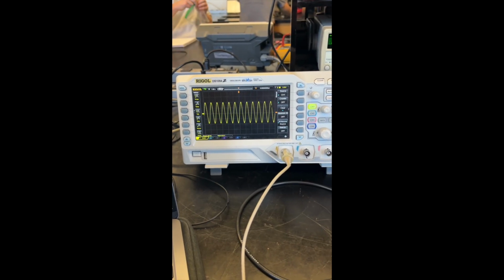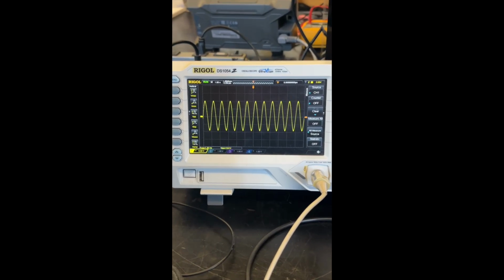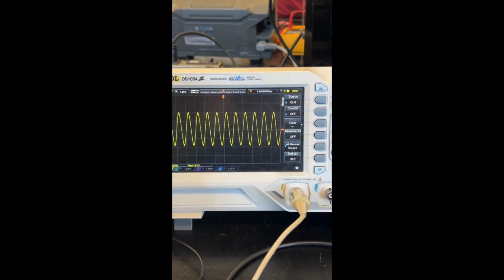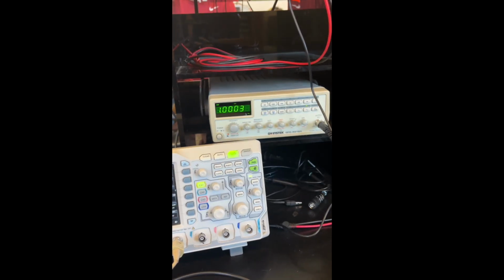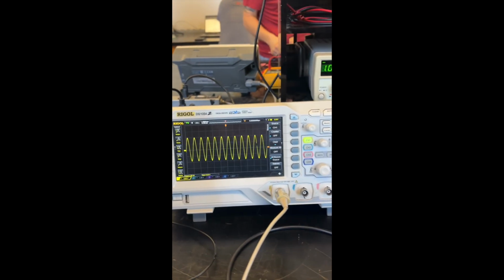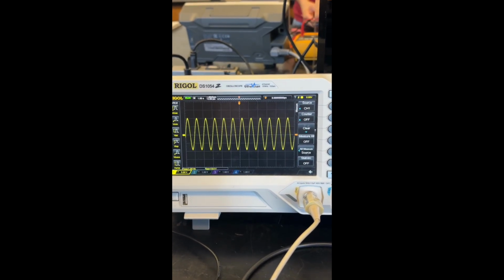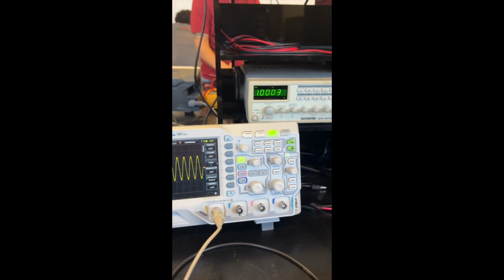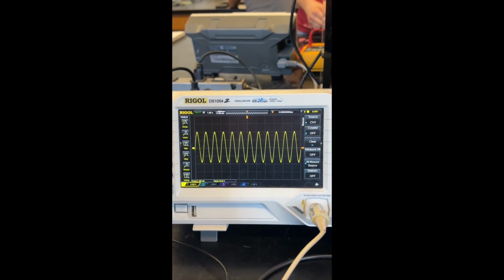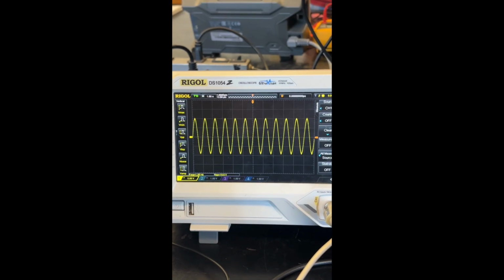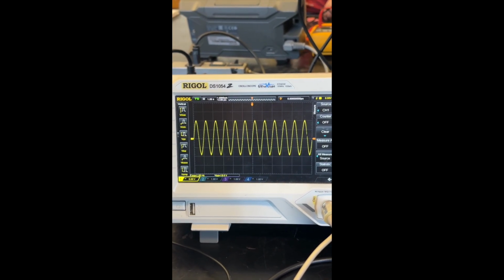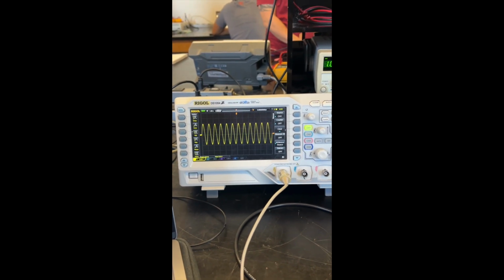All right, now we are on exercise 4. What I just did was find the correct voltage output with the correct frequency from my function generator. Since it's generating so slowly, I had to zoom out quite a bit for the time scale, and it was pretty much trial and error for getting the right amplitude. But now I'm getting a voltage from peak to peak of 19.6 with a frequency of 1 hertz. So now I will supply this to my circuit.